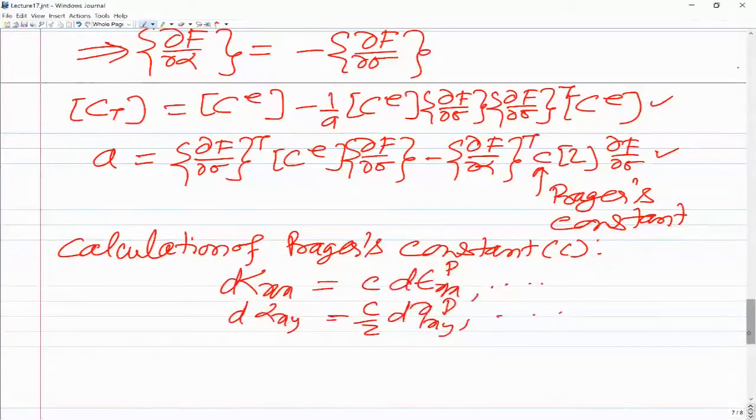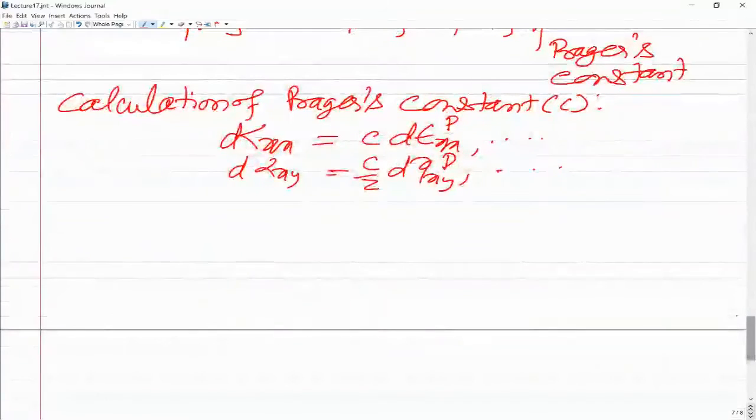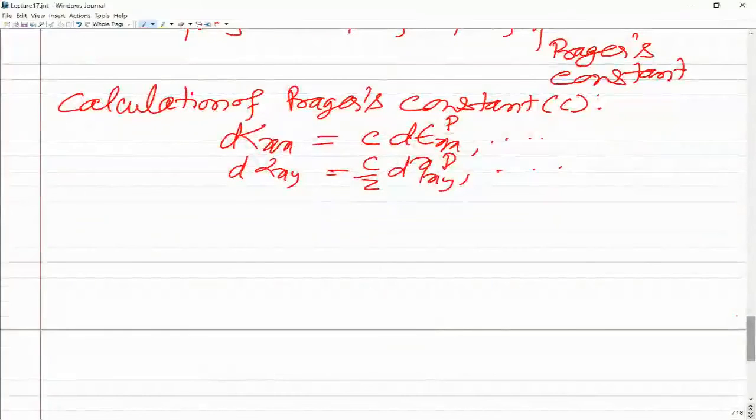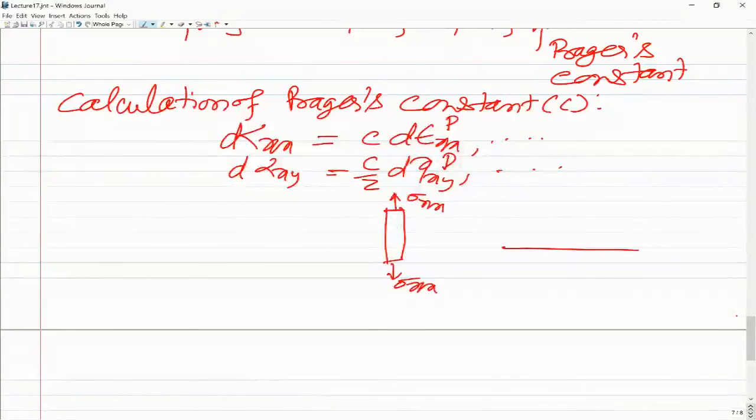Now consider again, we are going to get all the material parameter data from the uniaxial test. I have already explained that if you carry out the uniaxial test of the specimen, you have sigma xx and epsilon xx, and you get the true stress strain curve, and from that you can extract the relationship between sigma xx and epsilon xxp.